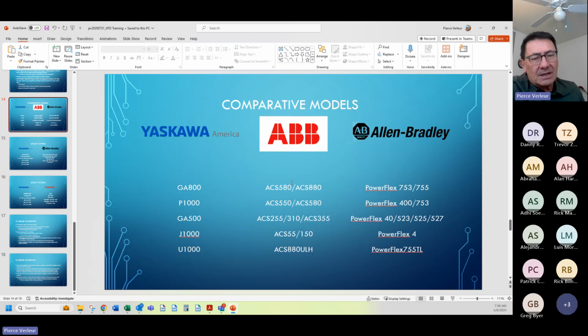And this is getting way in the weeds, but the temperature variation on the junction of the transistor for Yaskawa versus ABB on heavy, high-cycling applications, we've tested them side by side. And Yaskawa's temperature variation, for example, in the pump jack application, we're varying 5 to 7 centigrade on the junction, and ABB's variation is twice that.